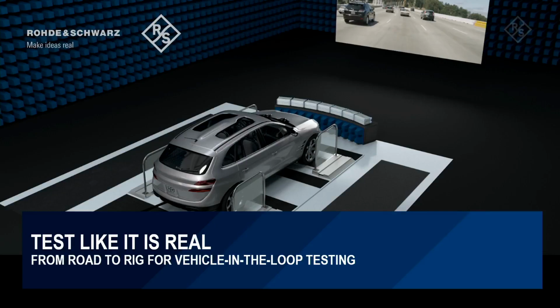But before we go more into hardware in the loop testing, I want to give you an idea of what else is possible with the instruments, for example, vehicle in the loop testing. If you have a new vehicle, a new platform with new ADAS AD functionality implemented, you want to validate at the end of the day whether the whole vehicle as a system is working as intended, and you therefore want to perform black box tests with the car, where there is no connection whatsoever between the test system and the car under test.